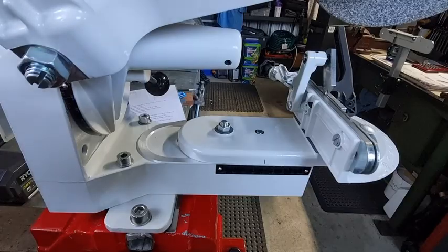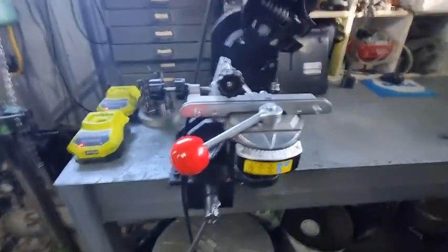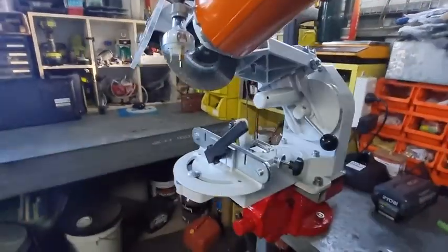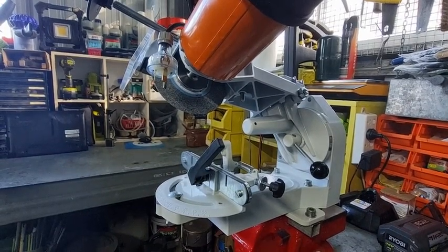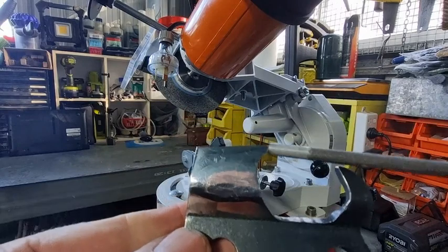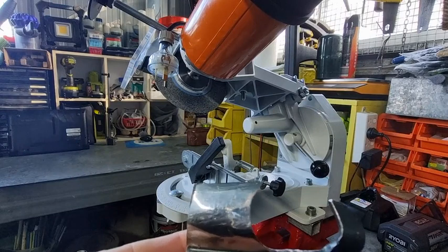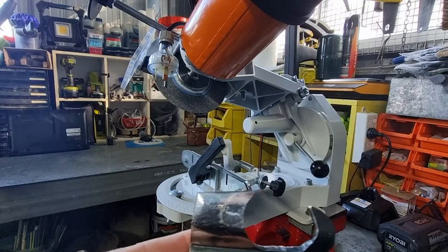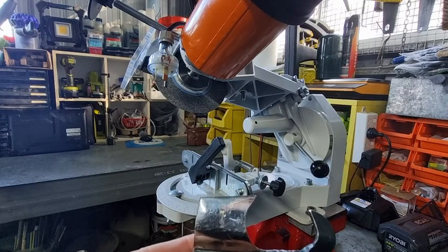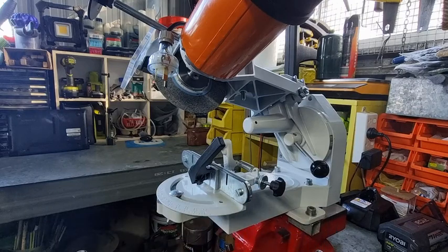If you look at the side of the tooth, what you want to avoid is having a bit of a large hook. If you've got a bit of a hook on a full chisel, this only refers to full chisel chain. So if you have too much of a hook here, it gets blunt quicker, and on real hardwood can even get damaged and bend over slightly. You mightn't be able to see it with your eyes, but if it's only 1 or 2 degrees, you may not see that with your eyes. And that is the reason I use a 10 degrees downward tilt.